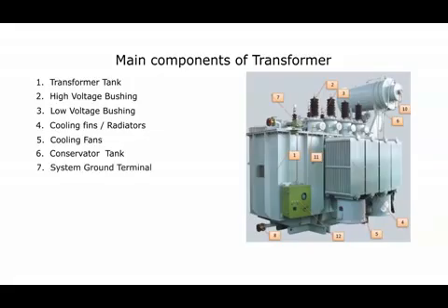System ground terminals are usually present in a power transformer whenever the connection type of the transformer windings has a star connection in it. This terminal can be found in line with the main terminals of the transformer. Drain valve can be usually found in the bottom part of the transformer tank. Drain valves are used whenever oil replacement is necessary. Through this valve, the replacement of oil in an oil-filled transformer can be easily done simply by opening this valve like that of a faucet.